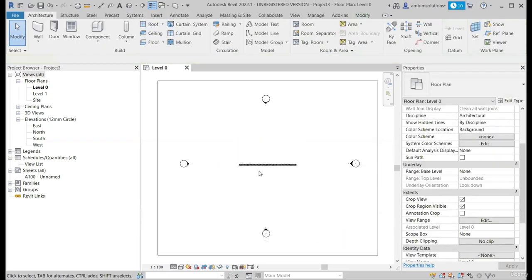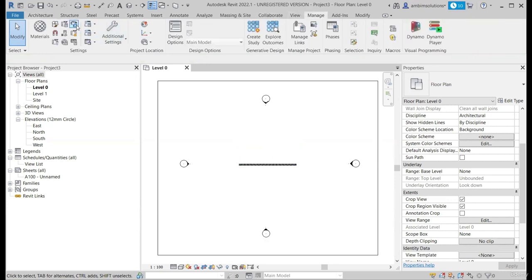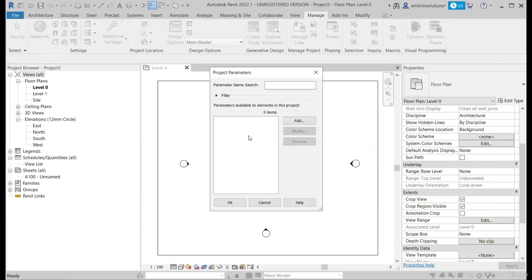We don't need to create the shared parameter again because we have created it previously. Whenever you are in a new file, you don't need to create the shared parameters again and again. If you remember, we created the test2 parameter as a project parameter. Are we able to see the test2 parameter in Manage? No, because the test2 parameter was only limited to that particular previous file. Project parameters can't be transferred from one file to another file, but shared parameters can.